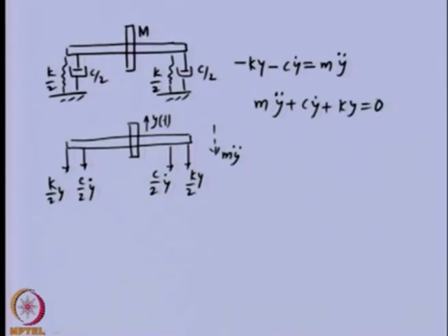like this. So, this equation of motion is a very popular equation of motion of a spring mass damper system, and to solve this for free vibration, obviously we need to assume the solution. Let us say we are assuming y equal to Y e to the power s t.